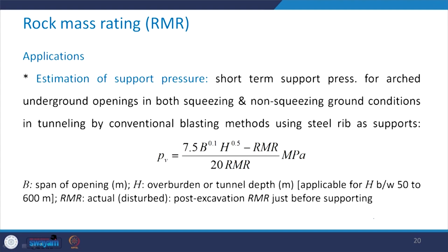The next application includes the estimation of support pressure. Short term support pressure for arched underground openings, both in squeezing and non-squeezing ground conditions. Right now I am not going to explain what we mean by squeezing and non-squeezing ground condition. When we go to the chapter on tunneling, there we will discuss all these things in detail. So for the time being, you just think about this situation, that RMR can also be used to estimate the support pressure for tunnels.